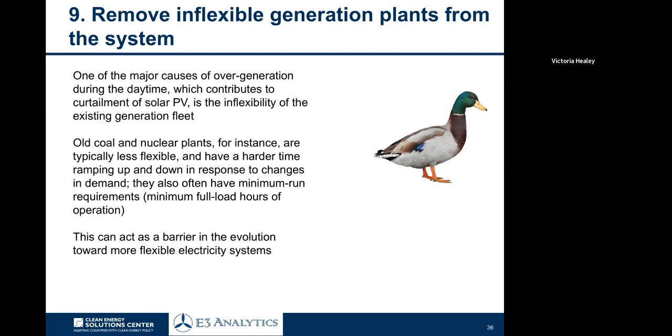A solar heavy electricity market with high penetration of solar PV does not need inflexible baseload. It needs flexible, load following, dispatchable, rapid response resources, including demand response. And we'll discuss that more at the end.